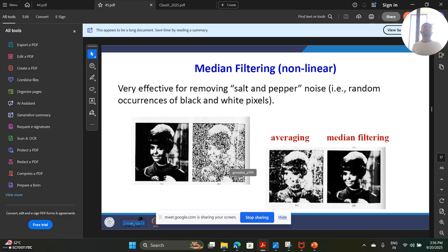Apart from that, when we work with SAR data, if you have heard of it, if you want to do any flood applications, we are working with SAR data because it's independent of weather. And SAR works in such a way that if water is there and nearby to water, land area is there, backscattering will be high from the land area, whereas backscattering from the water area will be very less.